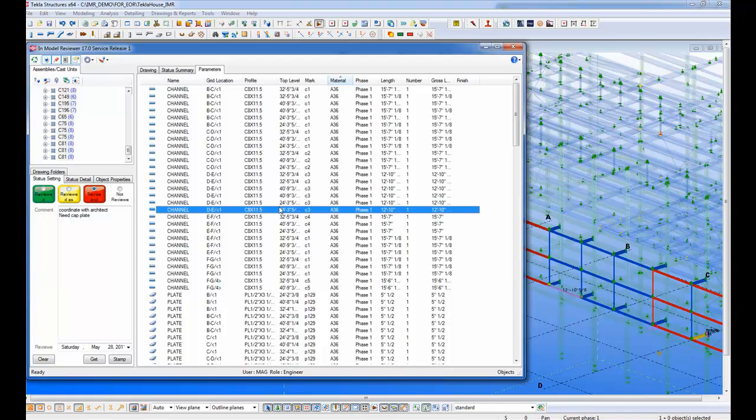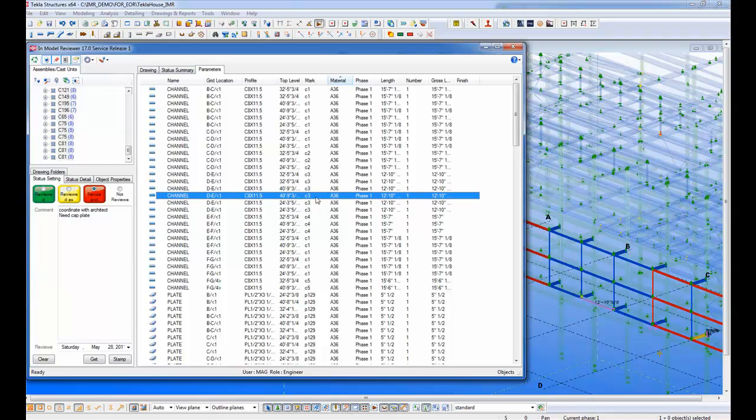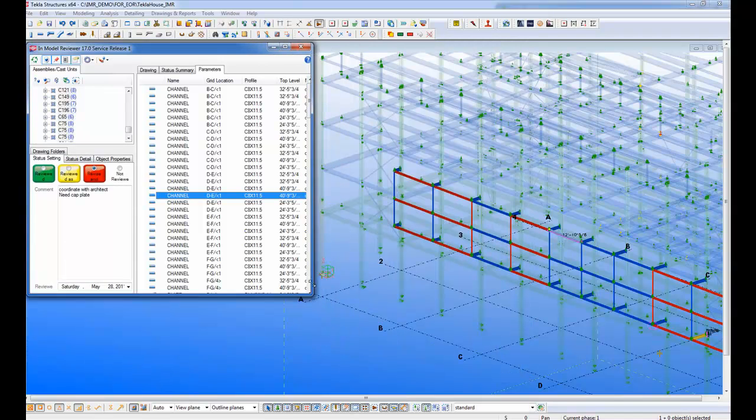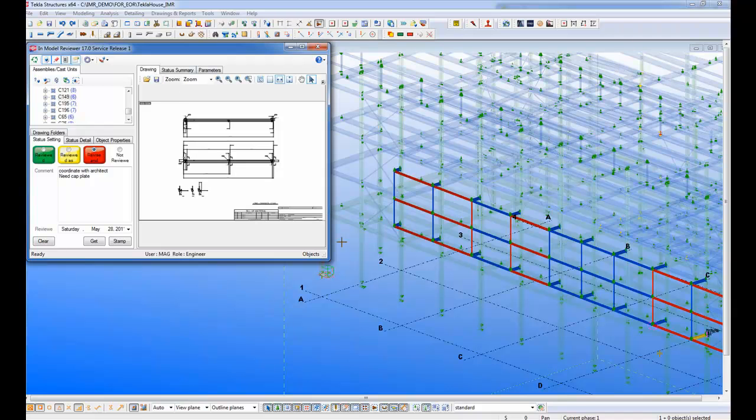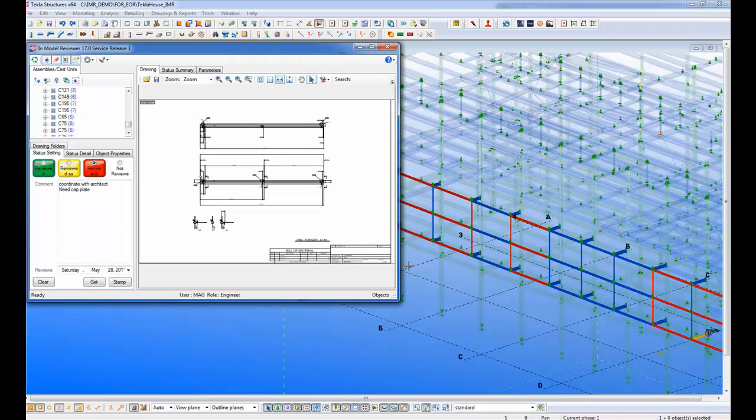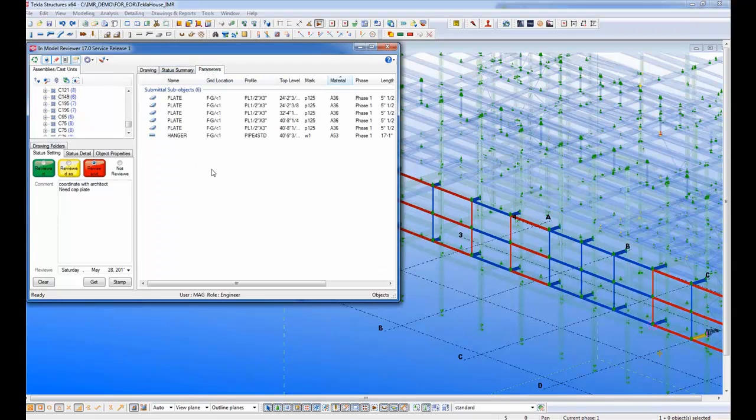And then once you find the ones that are in question, you can find out where they're at interactively in the model, and then actually come back in here and comment on them and isolate them. So really a more advanced way that you could think about reviewing shop drawings. And you can start off most likely doing it the traditional way, where you're going sheet by sheet, but then over time you'll see how comfortable it is to migrate over to looking at things holistically, looking at large amounts of data at one time.